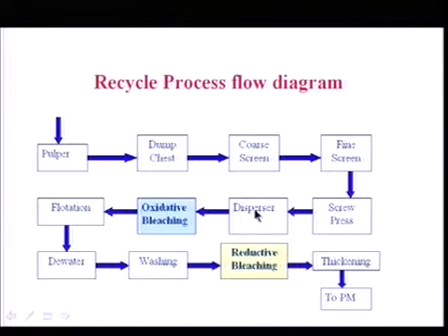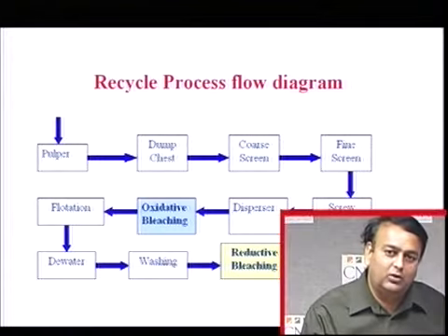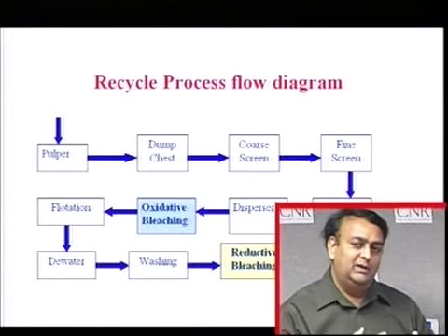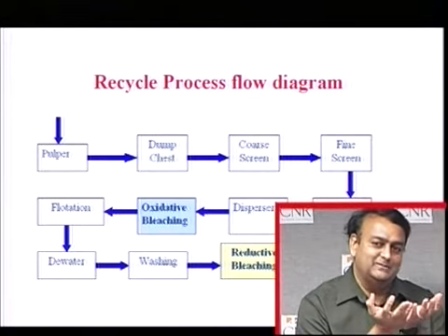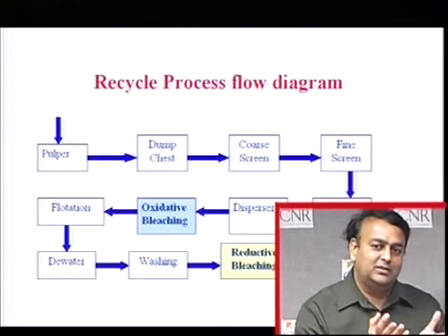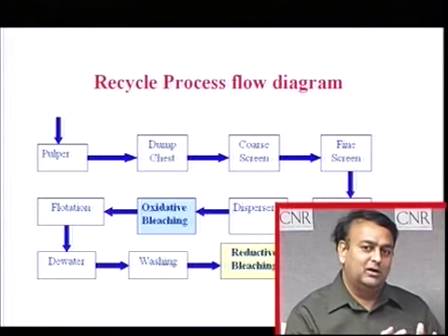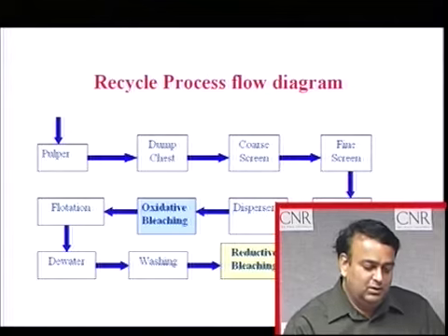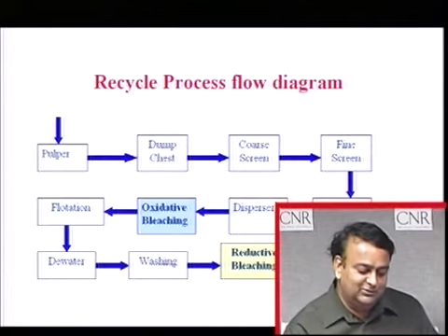In the disperser, the fiber rubbing action works on the ink and breaks the ink particles. So, there is good mixing of fiber, and you need to put energy into it, 3 to 4 horsepower days per ton. When you put energy into the fiber, it gets heated, so there is high temperature available. There is good mixing, higher consistency, high temperature, these are all available. It is ideal for peroxide type bleaching. So, you add peroxide chemical in the disperser.